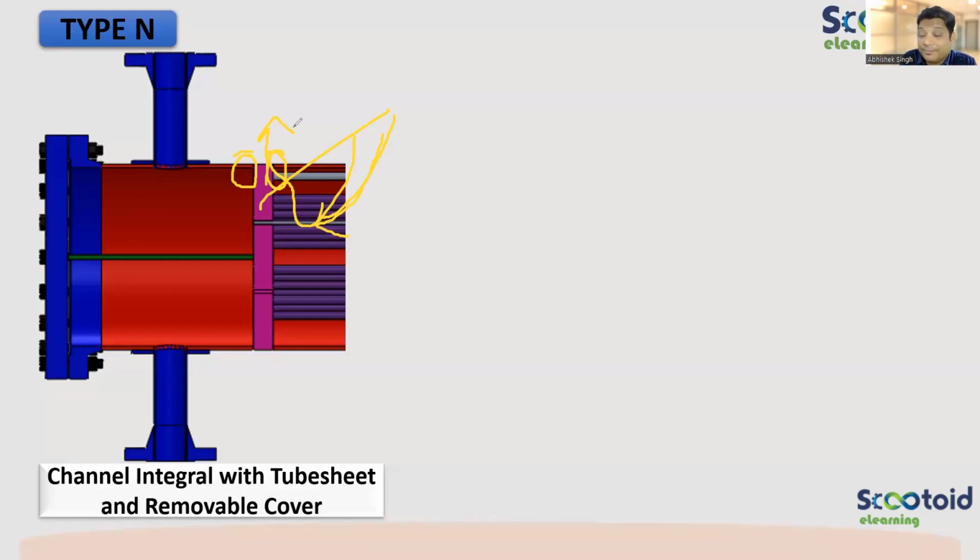So if my heat exchanger has a very hazardous fluid, you will want a joint with no gasket, completely welded. So you will go with welded construction. Absolutely right, Venkateshwar.